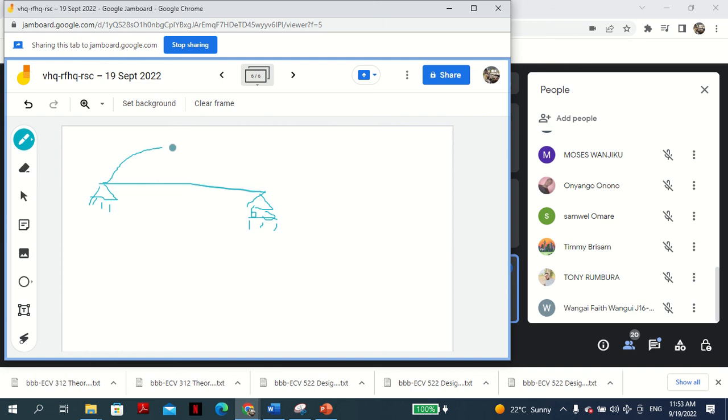This is the M over EI diagram. So this is A and this is B. Now you should know that theta A should be the VA, the reaction at A of the M over EI diagram. That's it.